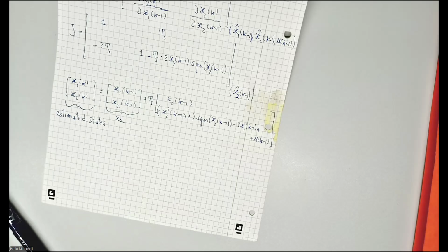The unscented Kalman filter I don't have time to explain, because the calculations are a little bit heavy, since it considers more points in the linearization, and then sums them up in a weighted mean value. Sigma points are the points in which we linearize the system, which is not one as in the extended, but more than one. How many? This is an open problem, I hope so.